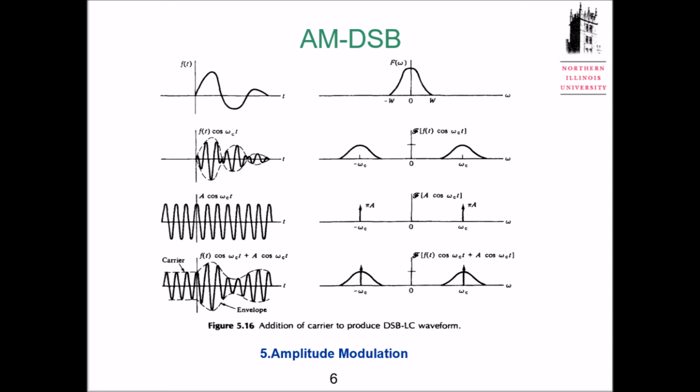So you choose omega c by your application. Channel 1, channel 2, channel 3, you just choose omega c and move it over there. Now, the carrier, A times cosine omega c, is a sinusoid. And its Fourier transform, like he just asked, is two impulses.